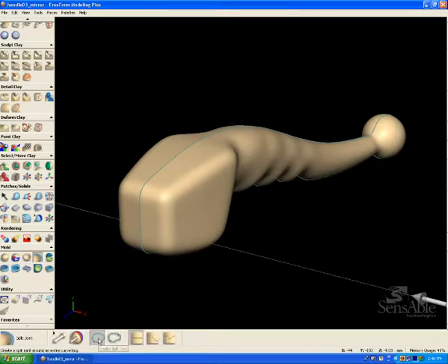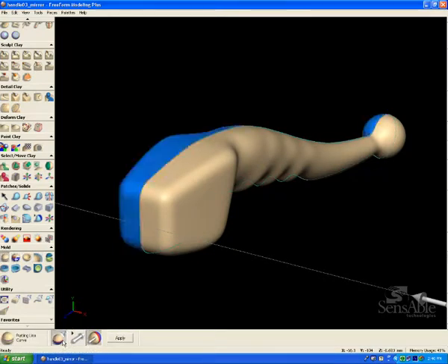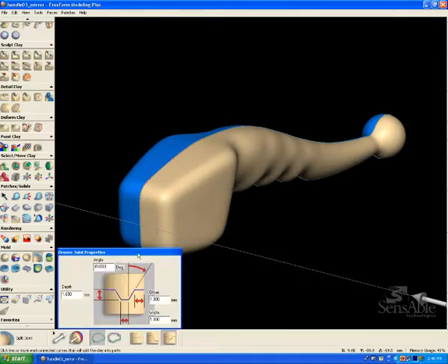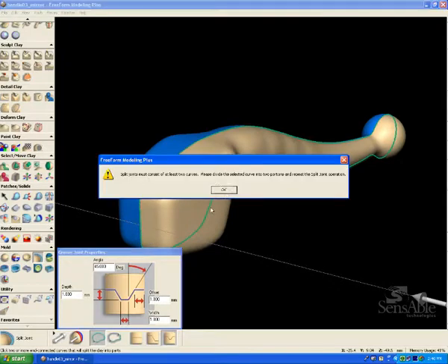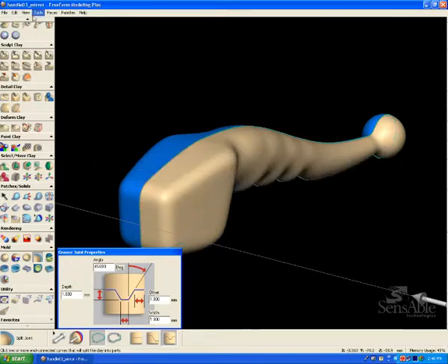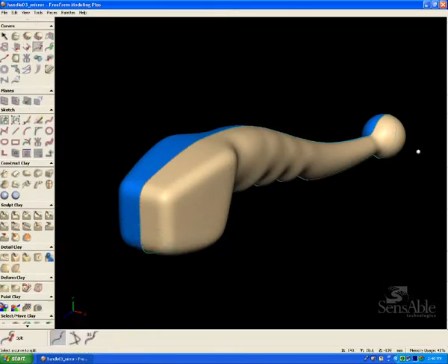It's what you want. So what I want to do now is, with that shell, create a split joint for the mold. So I'm just turning on the parting line colors again just to make sure that there's no issues with draft. It's nice and crisp. There's the blue and then there's the beige. There's no red. So what I'm doing now is setting the groove joint properties for some inserts on that split joint.